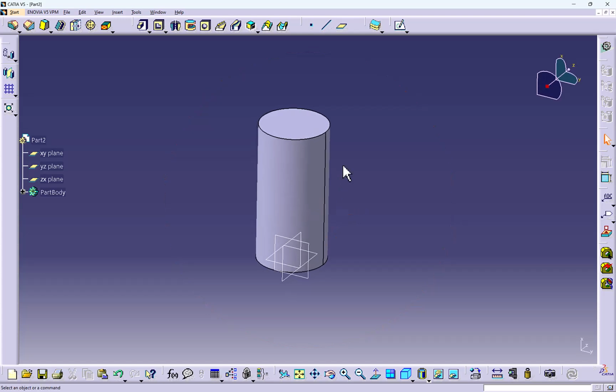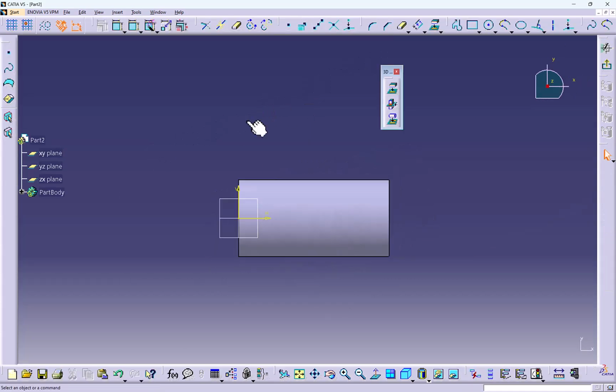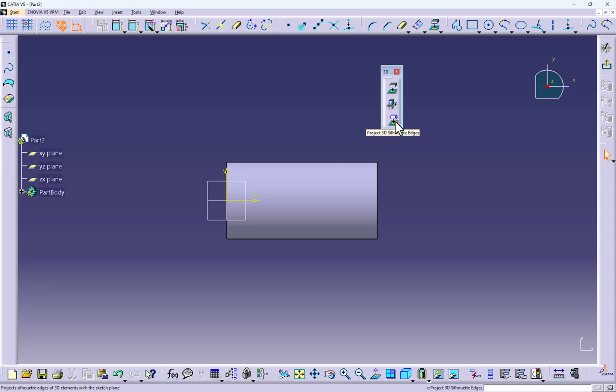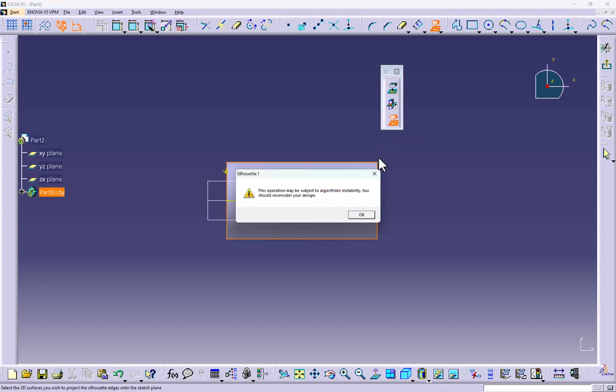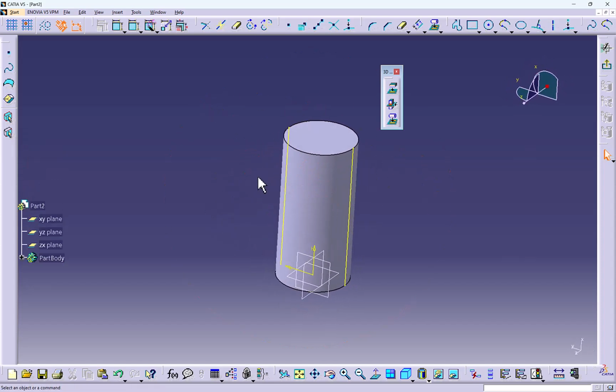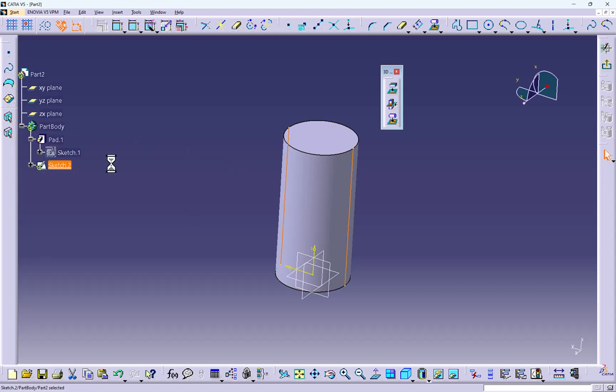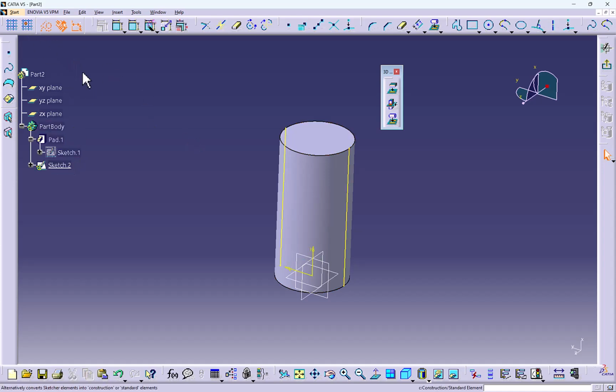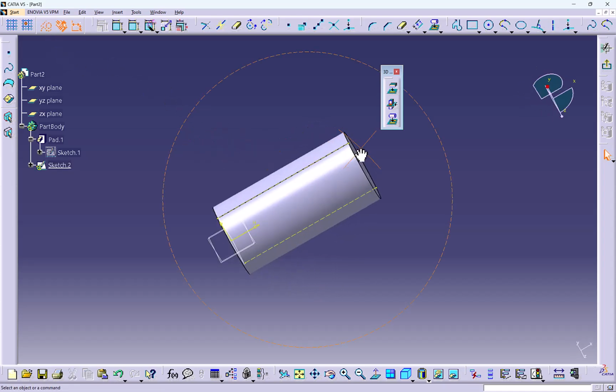Now what we do, we have to just put projections on this. I need lines from those faces on this plane. So select this plane and sketch on it. I'll use this option called project 3D silhouette edges. We'll select that circular body face and we can see that it got those edges. Sometimes we do not get a reference on the circular body faces to select the edges or faces properly. In that case, we project it and convert it to construction geometry, and we can use it as a reference element, because construction geometry will not come into our part.